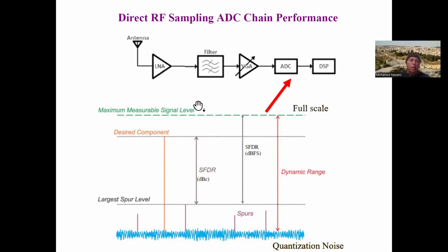Of course, we defined in the last sessions that even though the quantization level is here, we bring up the thermal noise from the front end so that we're at least above this by a margin, which is either 10, 15, sometimes 16 dB, and we will show numerical examples today on how we do that.